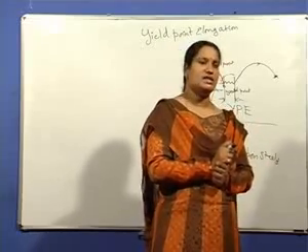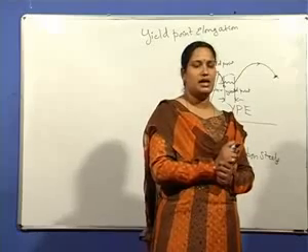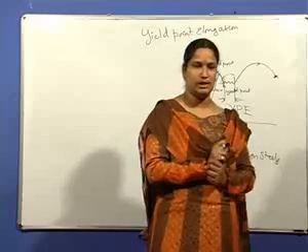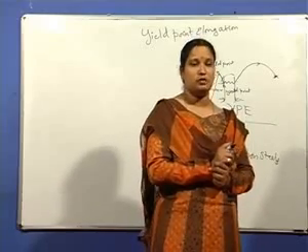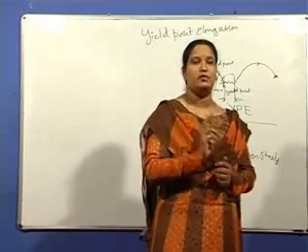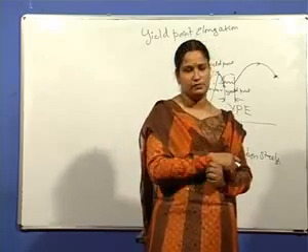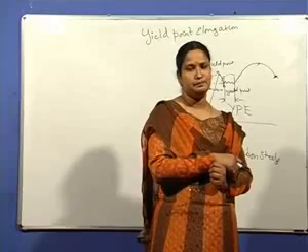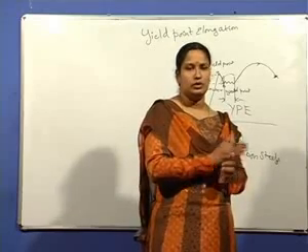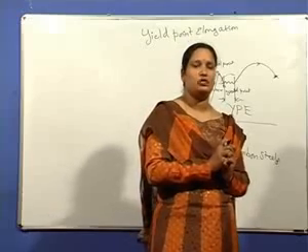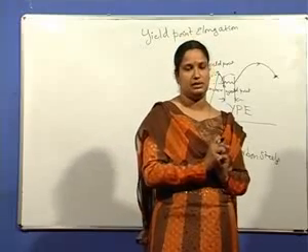Moreover, these atmospheres are not seen at slightly higher temperatures, greater than about 400 degrees centigrade, because of more thermal vibrations of the atoms, the solute atoms are torn away from these atmospheres. So this process ceases to operate at temperatures greater than 400 degrees centigrade.